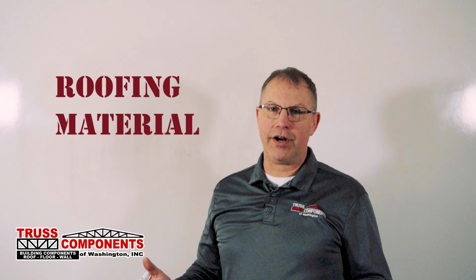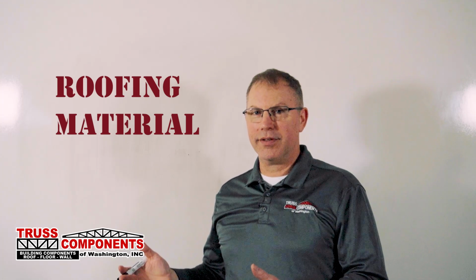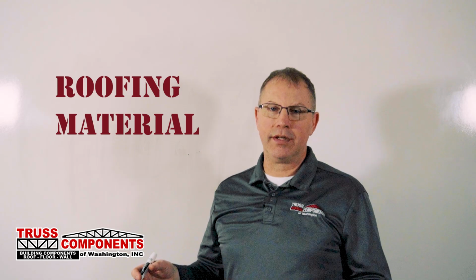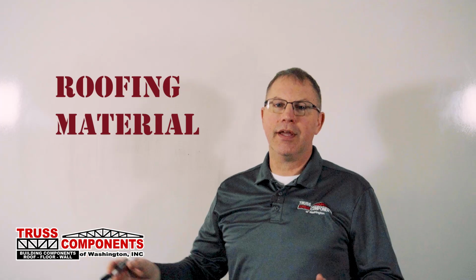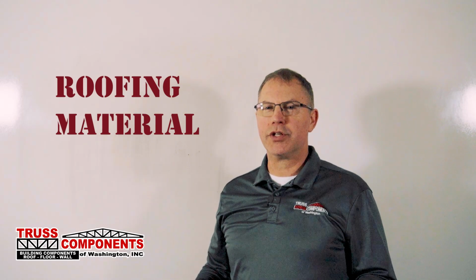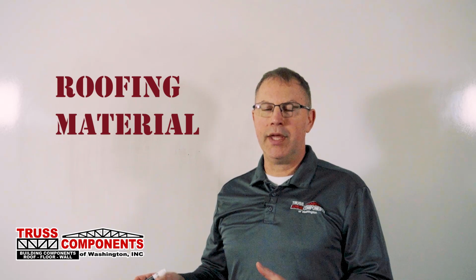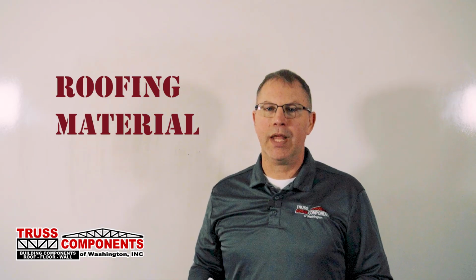The seventh thing that we'll need to know is what is your roofing material? And the reason we need to know that is to determine what weight the structure will be carrying. Composition roofing weighs more than metal roofing. Metal roofing and composition weigh less than tile roofing. And metal roofing over plywood or OSB weighs more than metal roofing does by itself. So we want to make sure that we are designing your trusses to be able to carry the load that's going to be put on them. And so you'll need to let us know what is the roofing material that you're going to use.